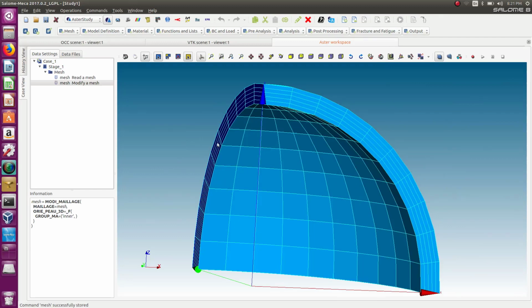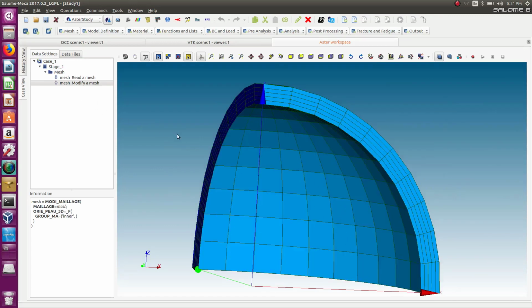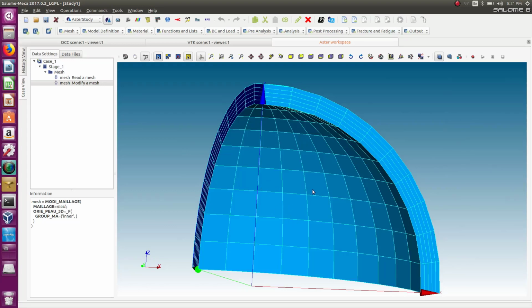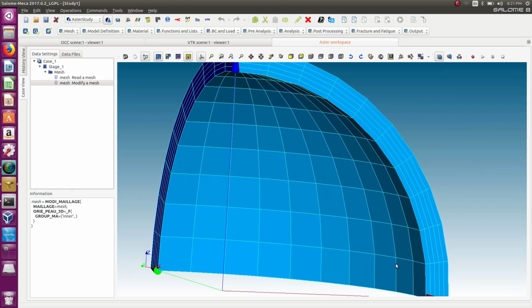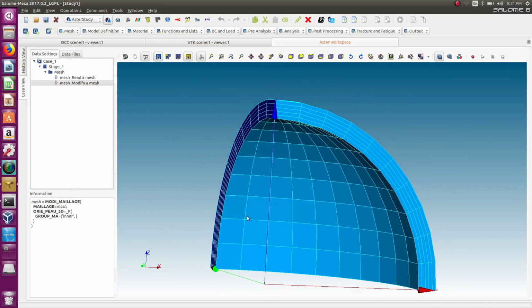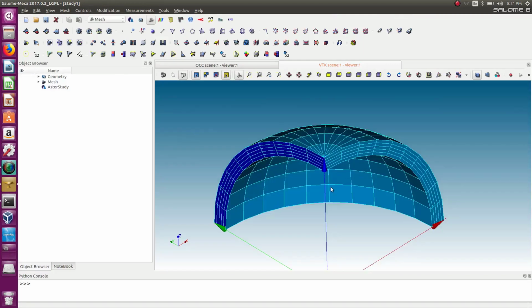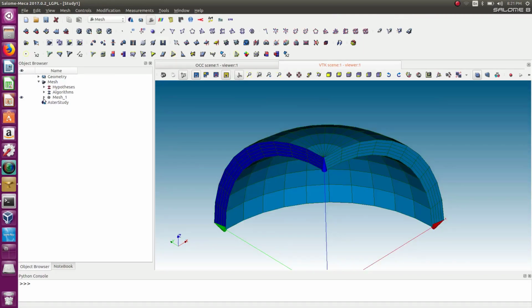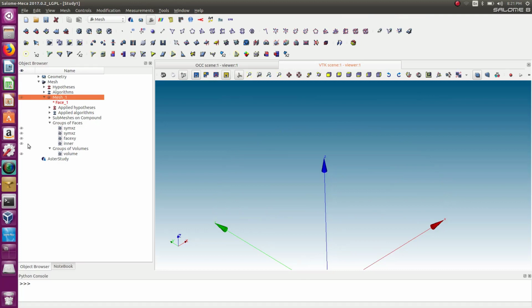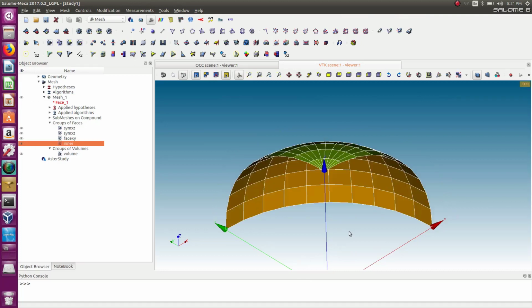So some people ask me, how do you know the orientation of the elements, basically? Because you choose an orientation, but you don't even know what this orientation is. Well, basically the orientation you choose is the orientation of the elements which are inside this group. And if you want to know exactly what this orientation is, you can see it like that. Let's go back into this and display only the inner face.